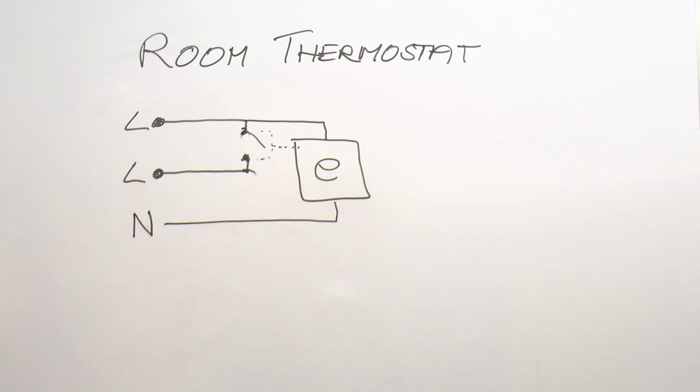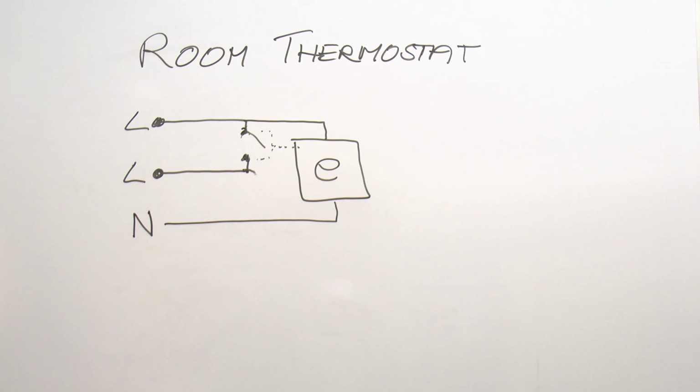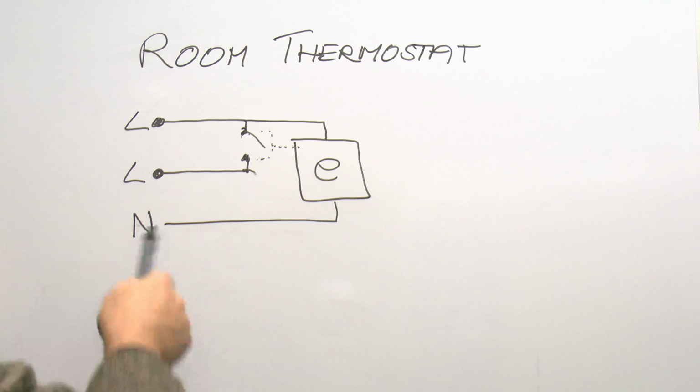Without it, the thermostat simply won't work. It'll just sit there on the wall doing absolutely nothing. And of course, the switch will remain permanently open and your heating simply won't work. And usually the ones with digital displays will require the additional electronic power. And also some of the dial ones, there's a Drayton one, which is a fairly common type, which although it has a dial on the front, the internal switching, again, is electronic. So without the power supply, it does not work.